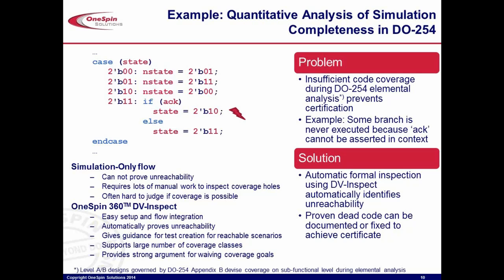So this is a solution that is now widely available in the industry, and is formal, to automatically detect that code, even in complex situations, which is obviously more productive, because it's an automated process that can either prove that a certain line of code is dead, so the designer's verification doesn't need to bang his head trying to hit that line, or try to go through some complicated analysis to waive it. No, this is unreachable. The tool can do it automatically.